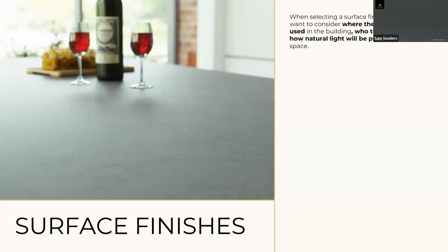And when using LRV, numbers can be an effective tool to guide your decision making. LRV, or light reflectance value, is a measurement of the total quantity of visible and usable light reflected by a surface when illuminated by a light source. Conversely, LRV also tells you how much light a color absorbs. With that in mind, we benefit most from a well-regulated dose of light.